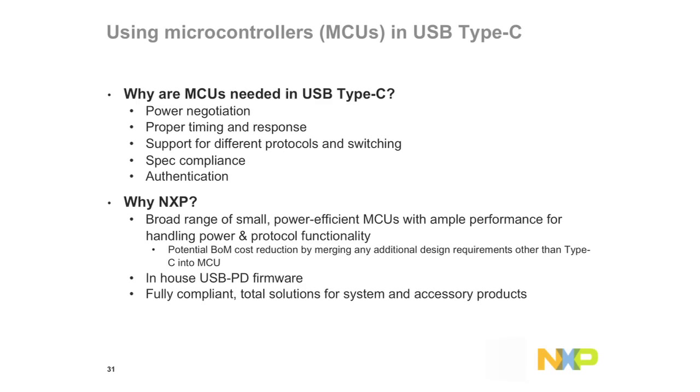So with all these protocols that can be going on between Type-C devices, you can imagine that there are strict timing requirements. And so really the MCU is needed in order to adhere to the spec and to make sure that, between different vendors, products can still be interoperable. So you can think of the microcontroller as kind of like a PD policy manager, as he mentioned. NXP has a broad portfolio of small, power-efficient microcontrollers.